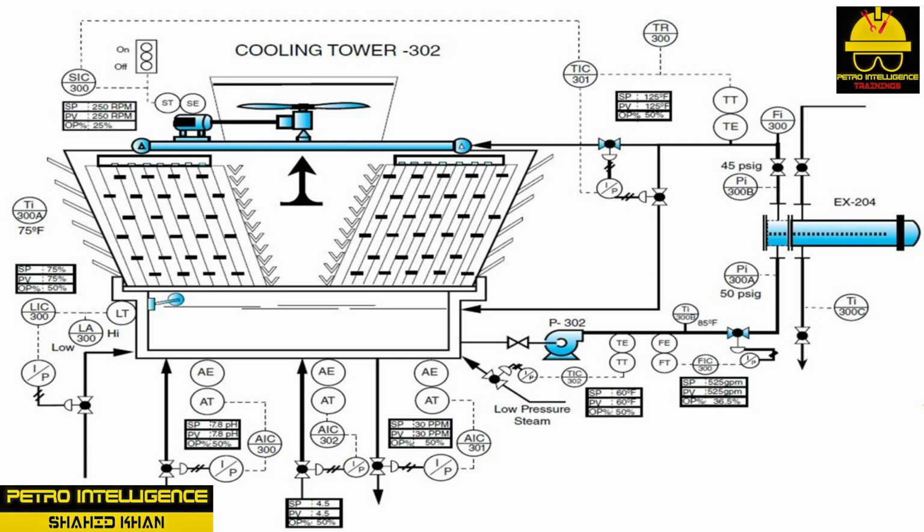Heat exchanger 204 is a horizontally mounted, shell-and-tube, multi-pass heat exchanger designed to condense vaporized butane into the liquid state. The pressure is 115 psig on the shell side and 50 psig on the tube side. The tube side contains cooling water from the cooling tower system. The shell side contains vapor or liquid butane at 115 psig.